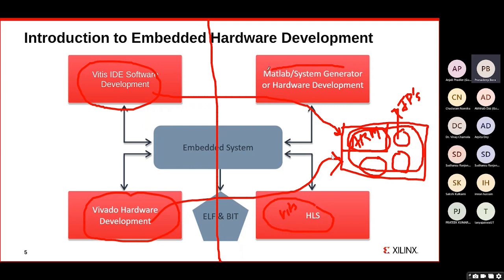Then we have MATLAB System Generator. So what we can do directly, MATLAB scripts can be converted into hardware IPs. So MATLAB algorithms are directly converted into hardware IPs. All those IPs, we can include in Vivado inside the IP catalog, and I can build the whole hardware of the embedded system in the Vivado Design Suite itself.